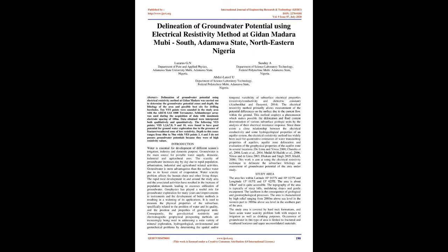Ten VES points were sounded in the study area with the ABEM SAS 1000 Terrameter. Schlumberger array was used during the acquisition of data with maximum electrode spacing of 100 m. Data obtained were interpreted both qualitatively and quantitatively.